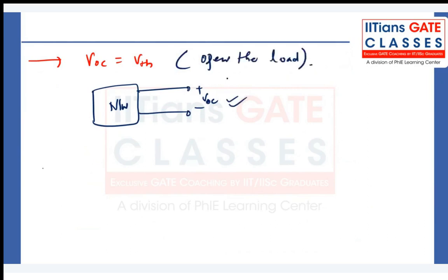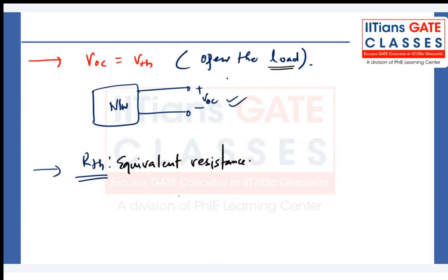And how to find RTH? Determining RTH is also simple. It is just like finding the equivalent resistance. Again you have to remove the load, and the method depends upon the network.